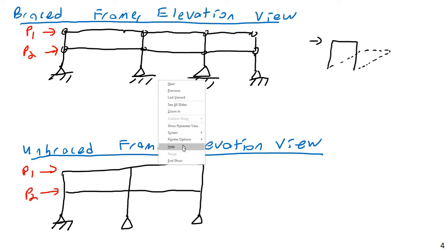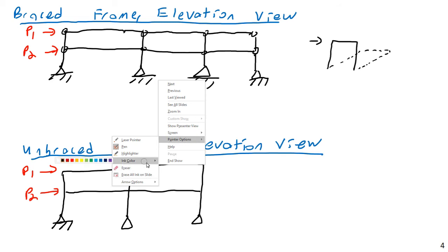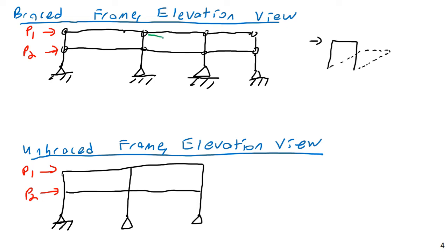And in terms of the angles here, in terms of what's an ideal angle, the most efficient angle would actually be at a 45-degree angle. That's no surprise. But depending on the geometry of the bays, and again, terminology, we refer to one of these rectangles in a frame as a bay, if you don't remember that from structural analysis. But we would call this a braced section, and this a leaner, and a leaner, and a leaner. So this is carrying the lateral load, and these are just sort of being held up aloft by this one.